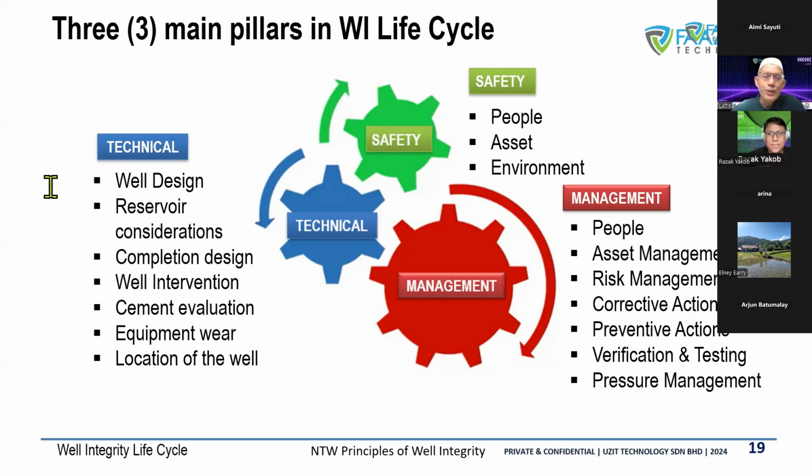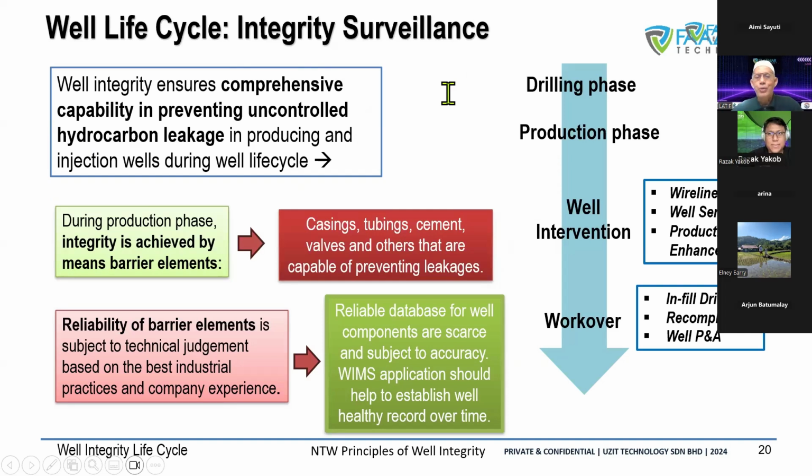Okay. Now let's go. For the integrity surveillance, as you know, when we put in the integrity, we have to put the surveillance to the well, understanding the strength of the well and the weaknesses. Like I mentioned, we have the drilling phase with different integrity surveillance, then we have the production phase, and then we will do repair work. When we do repair work, we pull out tubing. We have a barrier or cemented casing, and then we pull out tubing, so we lose the tubing. We have, of course, some brine in the hole, the production packer fluid, which is higher than your normal pressures. This is another barrier, but of course, if there is a perforation there, then it is open to the hole. If the formation is a weak zone, then you lose your hydrostatic. So the barrier condition in these phases can be different. So the worst case is P&A.